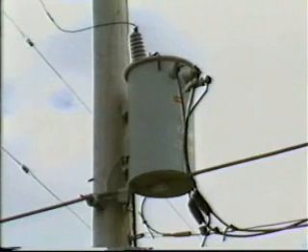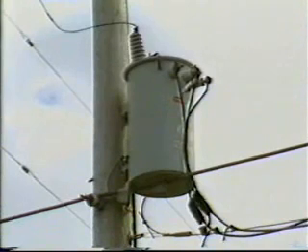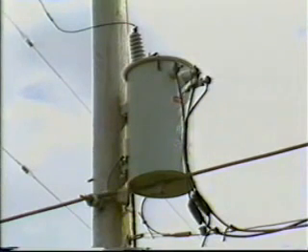The transformer tank is ruggedly designed to protect the core and coils from the elements. The tank top is sealed on tightly to prevent moisture from entering the transformer and contaminating the oil, which is needed for insulation and cooling. The volume of oil contained in the tank is quite small in comparison to the substation transformer. Hence, there is no need to install conservators or other systems that allow the oil to expand or contract and the tank to breathe.